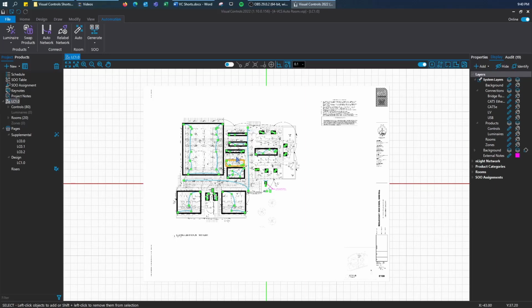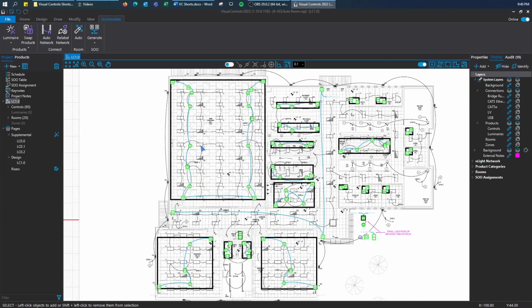A drawback to this tool, though, is that it actually doesn't draw rooms around the background room boundaries. It only draws it around the nLight daisy chains. This means you cannot use this tool if coverage patterns are required for your layout or submittal.